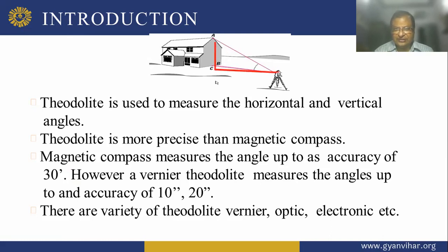So first you can draw, take the level, and find out this length. After that, at the top you will write this bearing. This is 90 degrees, and the bearing you have found out is 30 degrees. Then this is 60 degrees, because the total of the corners of a triangle is 180 degrees. So you can find out every length and every bearing.